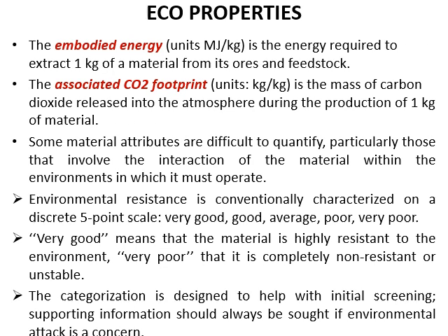Last but not least are the eco properties. The embodied energy, in units of megajoules per kilogram, is the energy required to extract 1 kilogram of a material from its ores and feedstocks. The associated carbon dioxide footprint, in units of kilograms per kilogram, is the mass of carbon dioxide released into the atmosphere during the production of 1 kilogram of material.